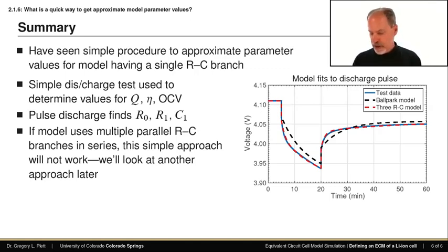And it's much better. It allows us to get a combination of time constants because, in actual fact, we learned from the Warburg impedance lesson, there are multiple time constants going on, not just one. And it's perhaps incredible, if you think back to that lesson, at how well the three resistor capacitor model approximates this voltage profile, given the fact that we know that to do it ideally we would need an infinite number of resistors and capacitors. So, using a pretty simple model, we can actually get quite a good result.